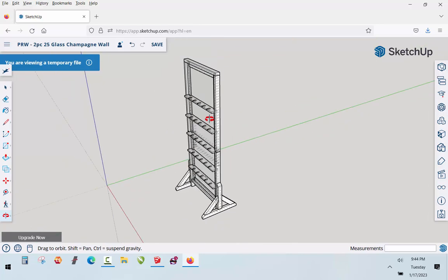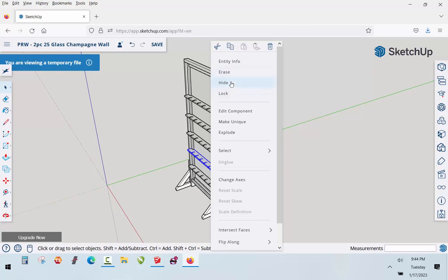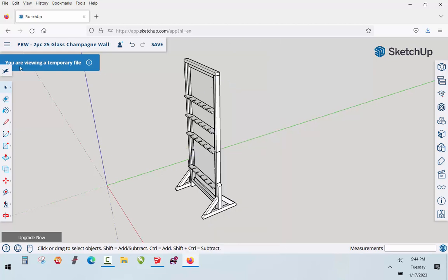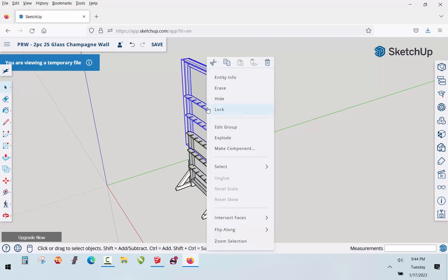The O key. K will turn on and off hidden geometry. We can select an item, right click, and we can hide it. And then we can use our eraser tool with our Alt key depressed. See how it pops back up. And then if we do want it to pop back up, then we click on it and it will come back full visibility. So that is our hide, and you can also just go to your pick tool here, and again you can just right click to hide items.